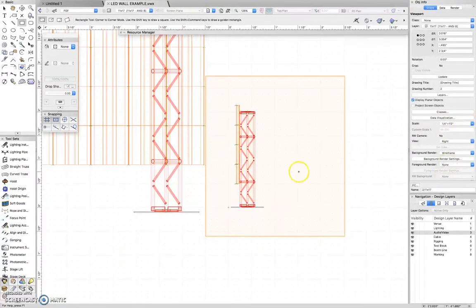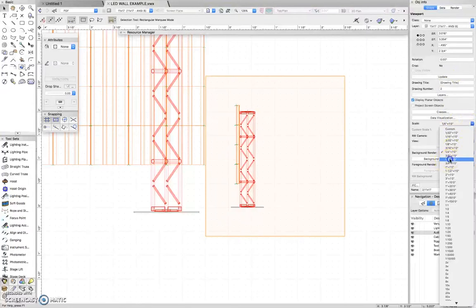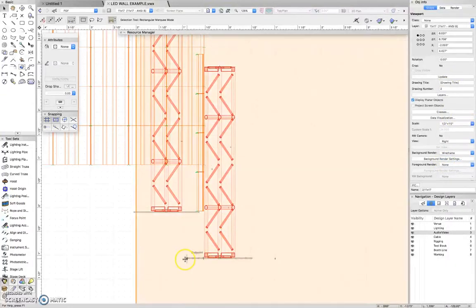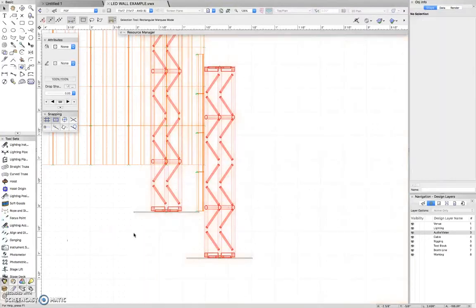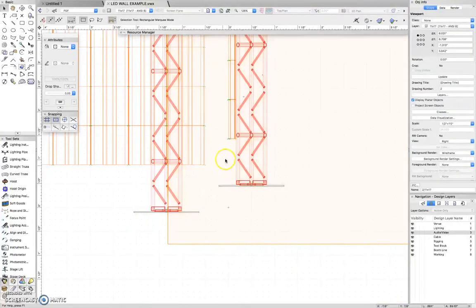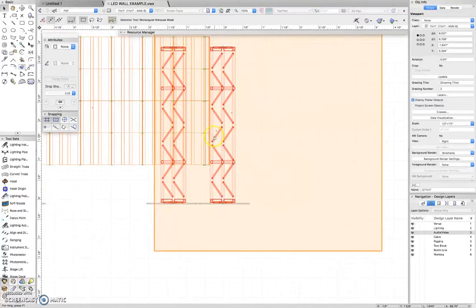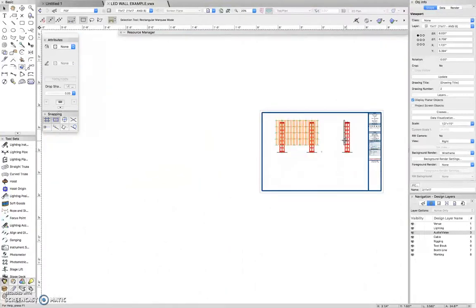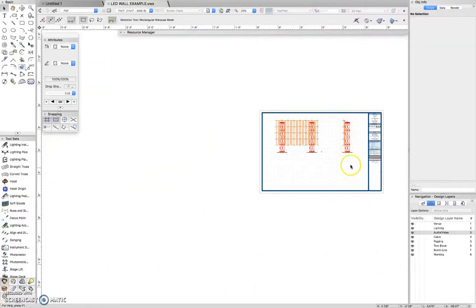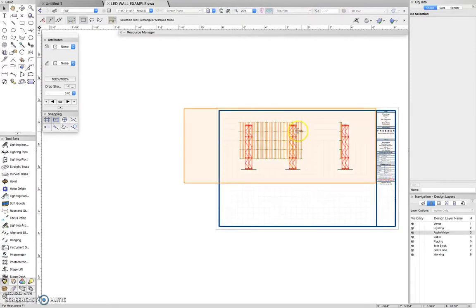Okay, I've got to fix the size. So hit X. You already have it selected, so you can edit the object info, and you've got your scale right here. If you remember, we went up to half inch. I'm going to line these up on this plane so that they sit nicely side by side. The reason I like doing a couple of different ones is because you can put dimensions on these and show how far forward the base plate is and all that stuff.